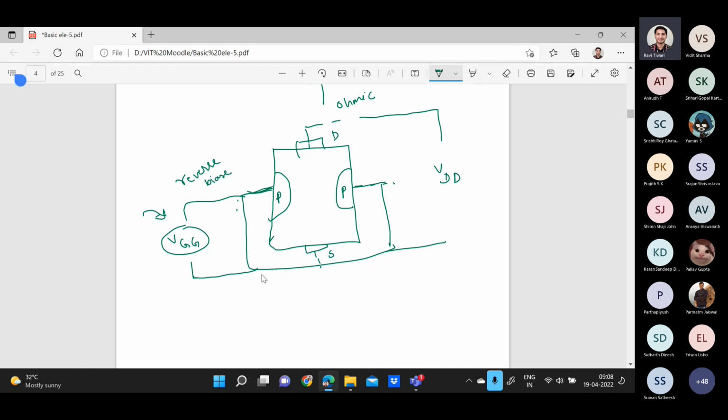Reverse bias, do you know, right? In the first case, case one, we are not applying this VDD. I am applying the reverse biasing only. So what will happen? Here I will apply this negative and positive like this, right? Negative to the P terminal, what will it do? It will increase the depletion region, right? This negative will repel the holes, which are the majority carrier, in this direction, and it will increase this depletion region, and it will expand.